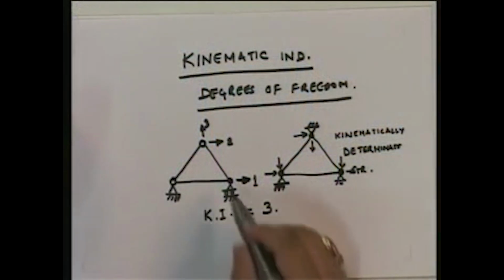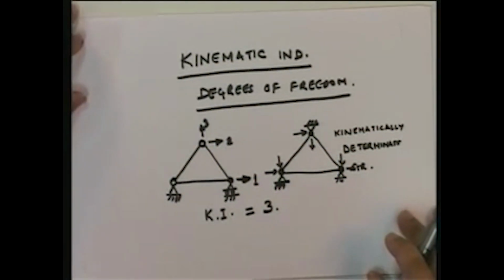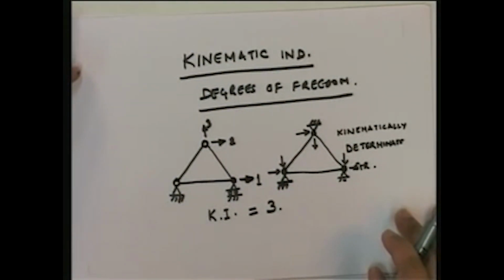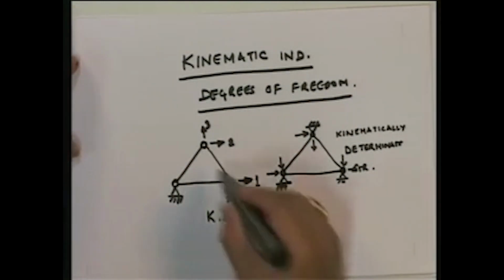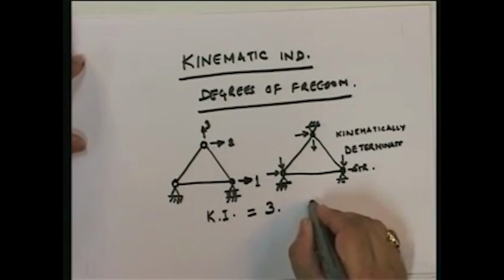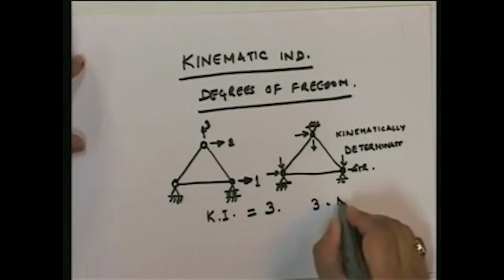So therefore, if you have a truss, any joint in the truss can move in the plane. And what you need to look at is what are the restraints. So now I can look at it this way. Let me redefine this problem. How many nodes? So I'm not going to do an algorithmic way of getting the kinematic indeterminacy. How many nodes? This structure has 3 nodes.